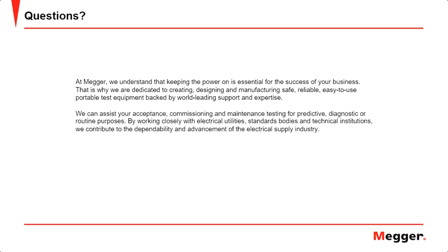PI is a 10-minute test, right? You do your 1 minute to 10-minute ratio in a polarization index. That is specifically to evaluate the polarization of the cable and say whether your 1 minute to 10-minute ratio is good or not. Obviously, you should have your readings increasing because you're polarizing the cable, so your resistance should be going higher.